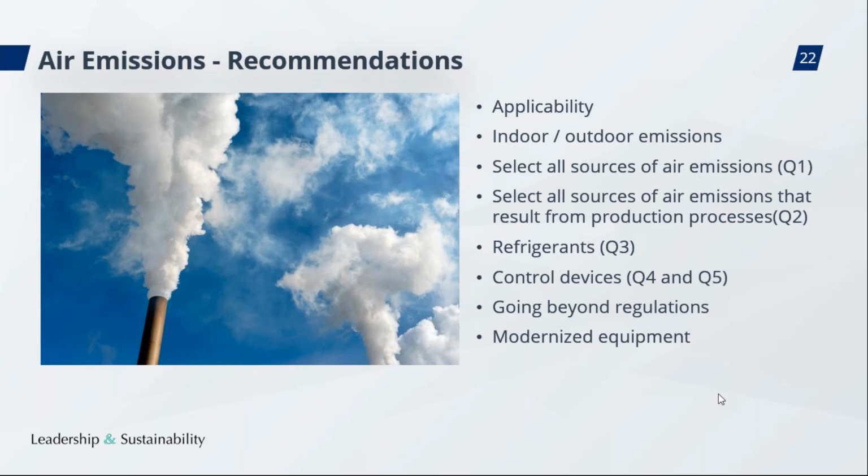Question 7 is related to your emission control method. One example of modernized machinery is an electrostatic precipitator or flue gas desulfurization. Also, improvement or enhancement of the fuel system or switching to an alternative or cleaner fuel could be considered as an abatement process. For example, using natural gas instead of fuel oil in a boiler.